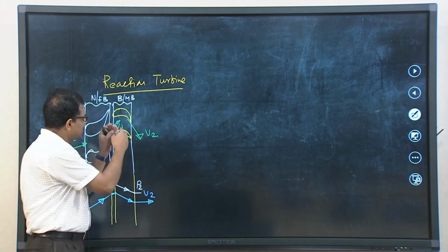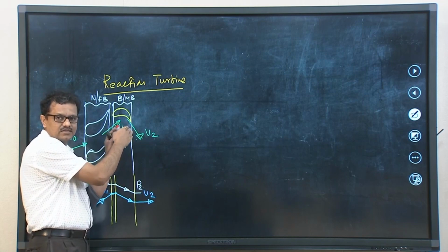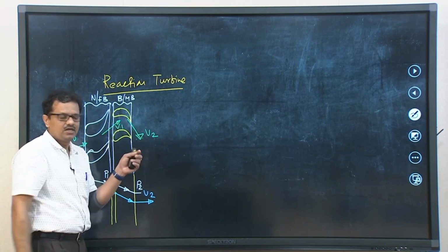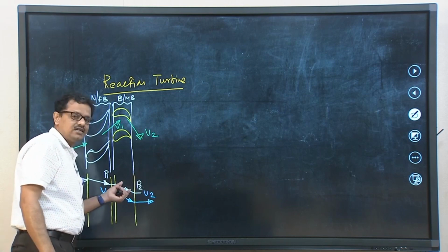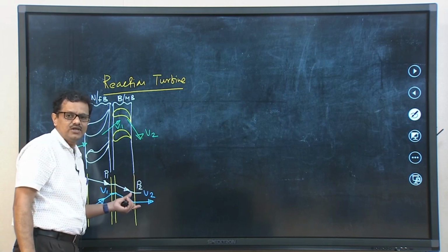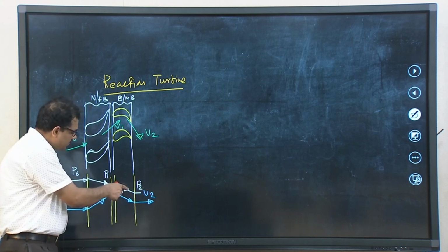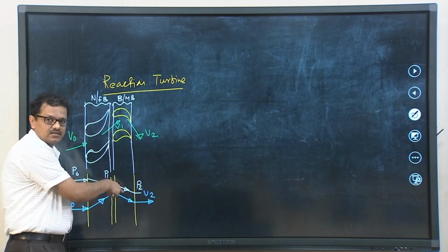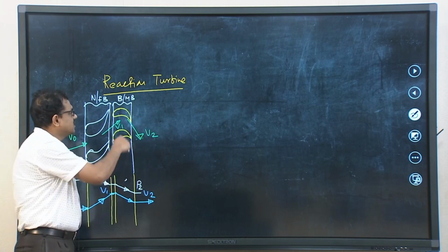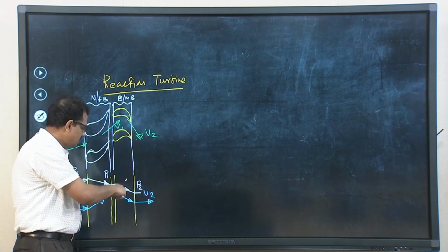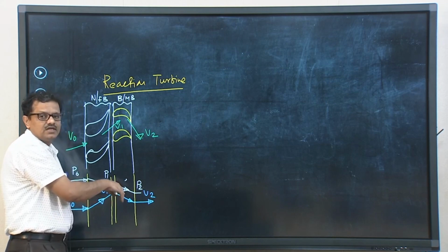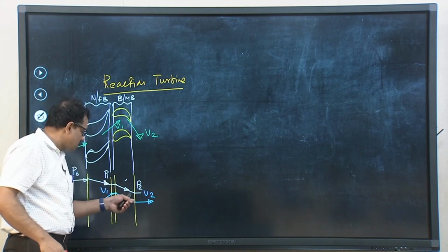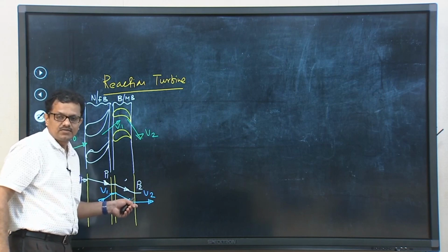So, steam will be deflected by the blades. Over and above, there is also a little gain in kinetic energy of the jet, and that is due to the drop in pressure, because velocity will increase. If pressure remained constant while steam is passing through the moving blades, in that case velocity would have decreased even more than what we can see here.